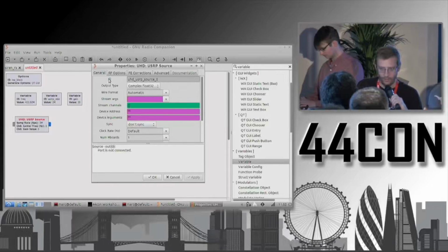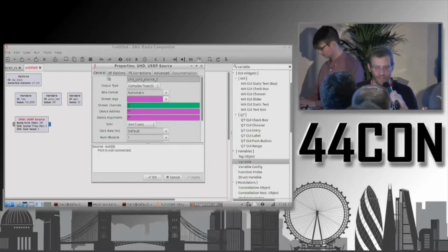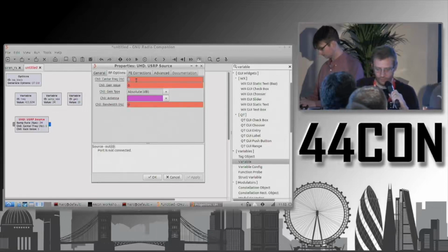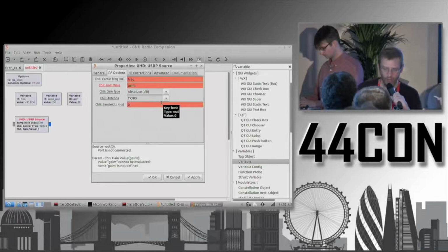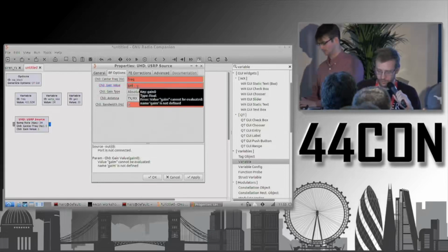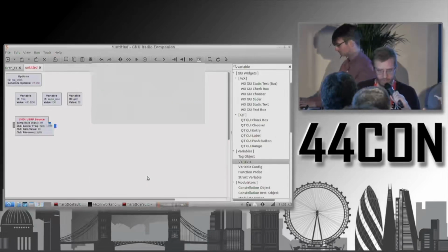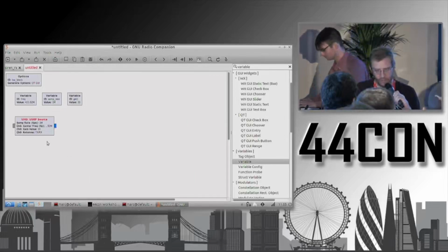And then in the properties for the blocks on the GNU Radio Companion flow graphs, you can fill in the values with the names of these variables, and it's just setting Python variables in these underlying objects. So we'll set our frequency to FREQ and set the gain to gain. In this case, I'm setting an antenna that's specific to the radio I'm using, so that won't apply with the RTL SDRs. And so now we have this block configured to take radio data in at 433.92 megahertz.